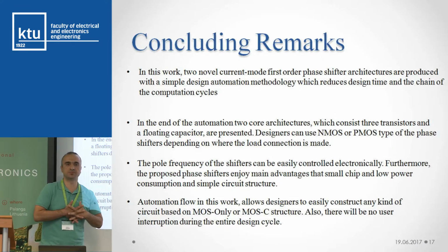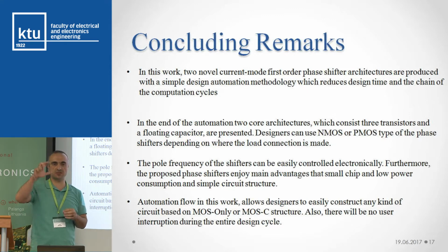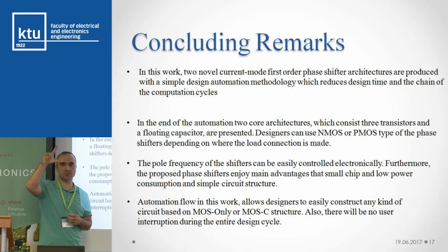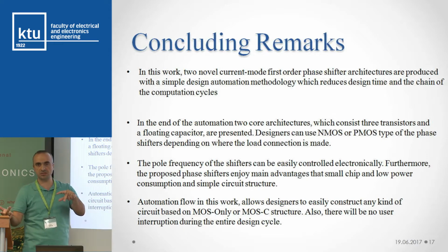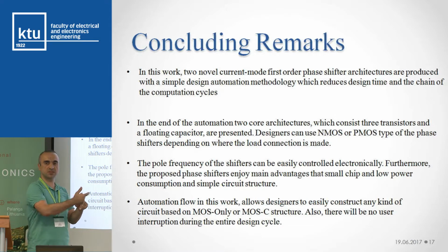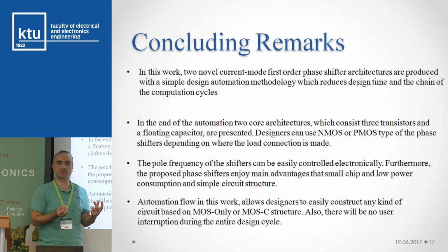To conclude, we use Mathematica, MATLAB, and also LT-SPICE. We start from modeling the transistor as a 3-terminal device, randomly connecting them, generating the transfer function. If it is a candidate, we use a MATLAB script to generate the outputs using the user specs, input values.